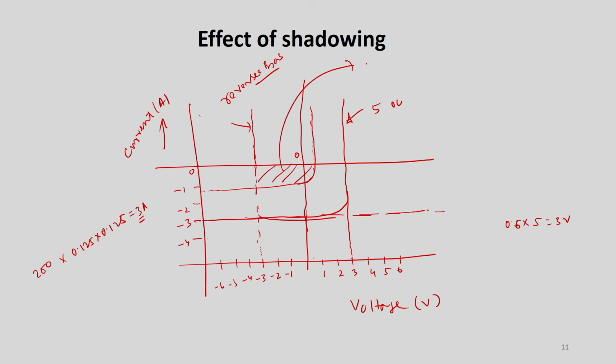The dissipated energy is this one. What I have drawn here for this is 5 volt. This is an IV characteristics curve for the scenario we discussed in the last slides. There are 5 cells which are producing energy. For 5 cells, what will be the voltage? Every cell has 0.6 volt of OC, and then you have 5, so it will be 3 volt.